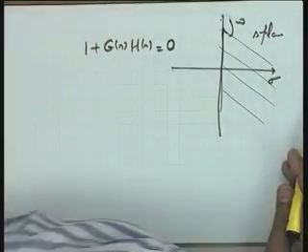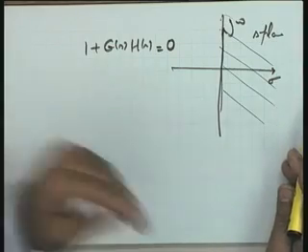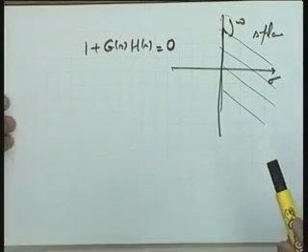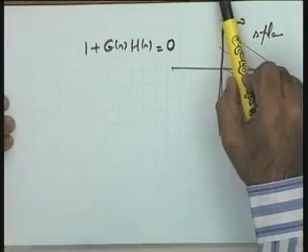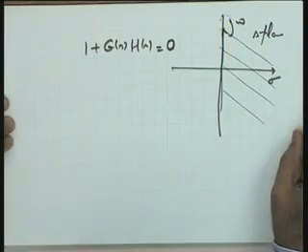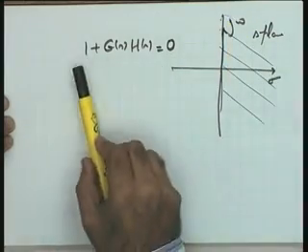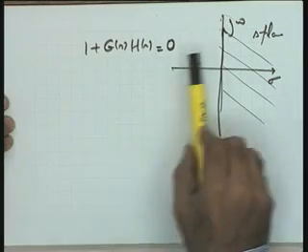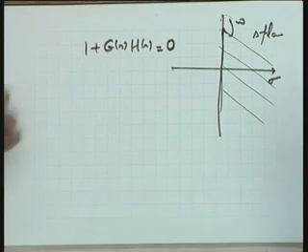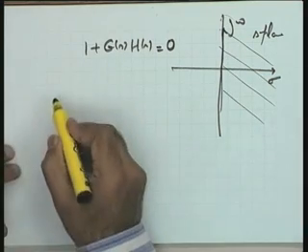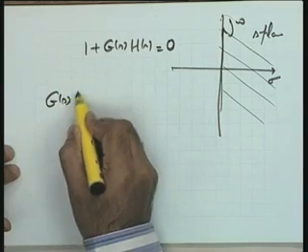Marginal stability I am taking to the unstable region. Okay? So my statement which I gave, I repeat here, that if there is no point on the imaginary axis or in the right half of the S plane for which 1 plus G(s)H(s) equals 0, in that particular case I say that the system is stable. I hope this point is well taken. Fine. Let me talk of G(s)H(s).